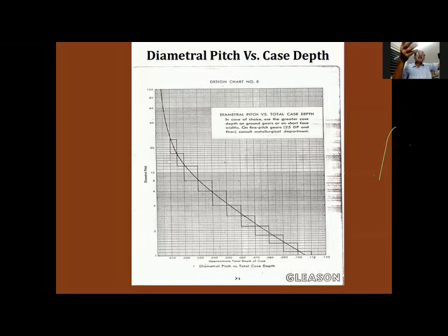If it is more than that, let's say 0.8 to 1.2, typical tolerance is 0.2 or 0.25 millimeter plus minus on the nominal value. And beyond, let's say 1.3, 1.4 millimeter, the tolerance is generally more, 0.4 or even 0.5 total tolerance. Okay. So next slide, please.